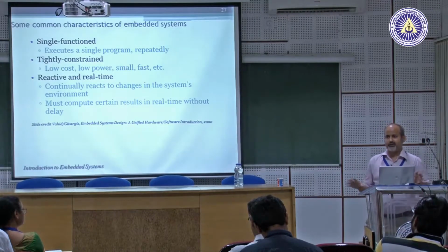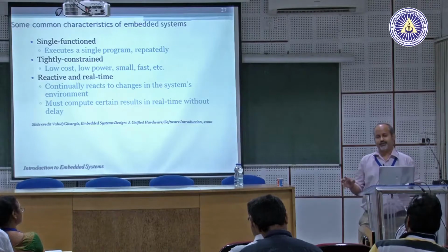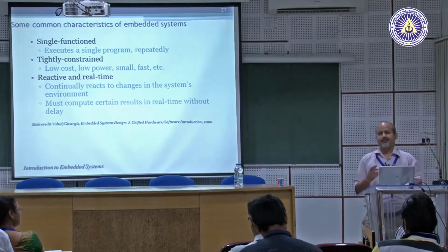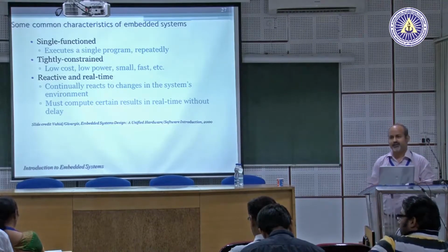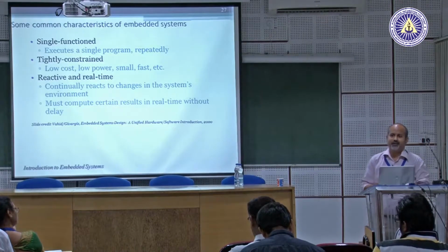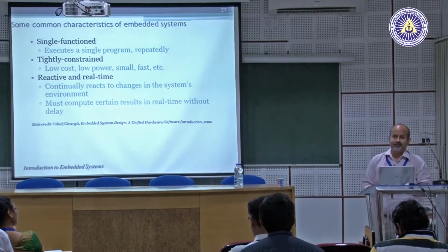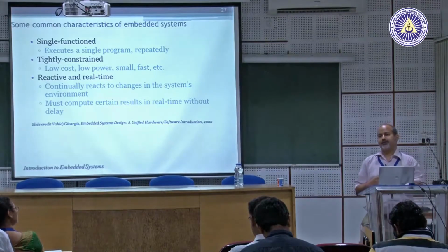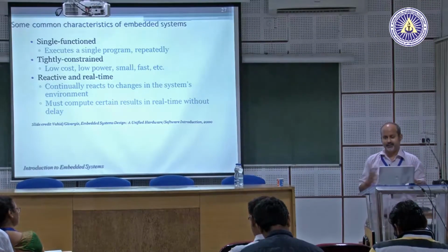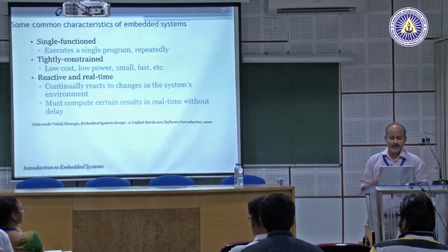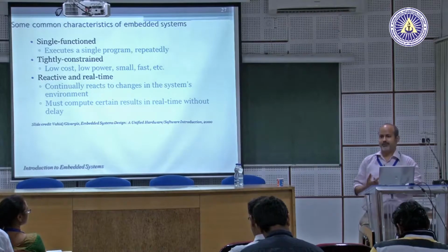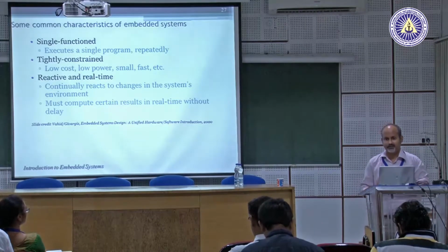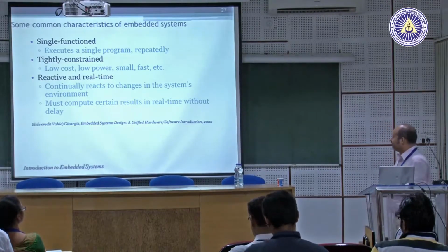That's why you have so many microprocessors. You could have taken a much larger, more powerful processor and integrated all these functions, but that's not normally done. The reason is that it gives you much better fault tolerance. For example, if your air condition unit is in the same processor as your brake, and the air conditioner fails, maybe your brake will also fail, and that's not good, right? So you want to separate them.